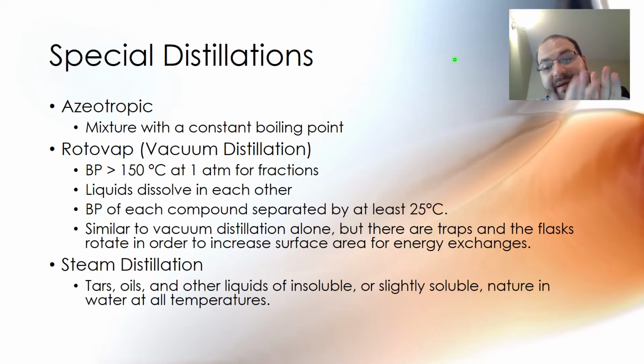We have in the past had some questions on the quizzes where you look at the graph, like the one I showed you, where you have the upper boundary and the bottom boundary, and you have the theoretical plates moving in the boundary, and you have some mole fraction that you're looking at for a particular compound, and you start at that particular concentration. I think I put one of these in the extra credit assignment that I've put up on iLearn, so you can play with it and kind of see how it works. And you follow along and you determine how many theoretical plates you need for the separation. And you can also tell how many you could have in the column itself by going through it.